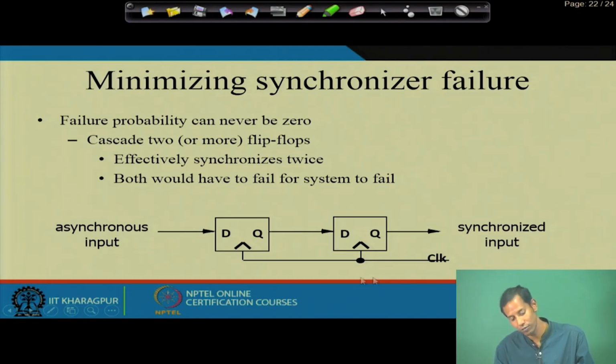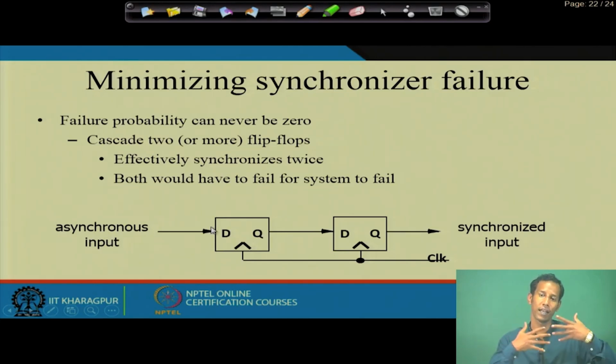So whenever we are giving signals to our designed IC, they should be passed through a synchronizer. The inputs may be different at different times, and they may be multi-bit. So all the inputs are synchronized and go to the corresponding IC at the same time, depending on the same event.